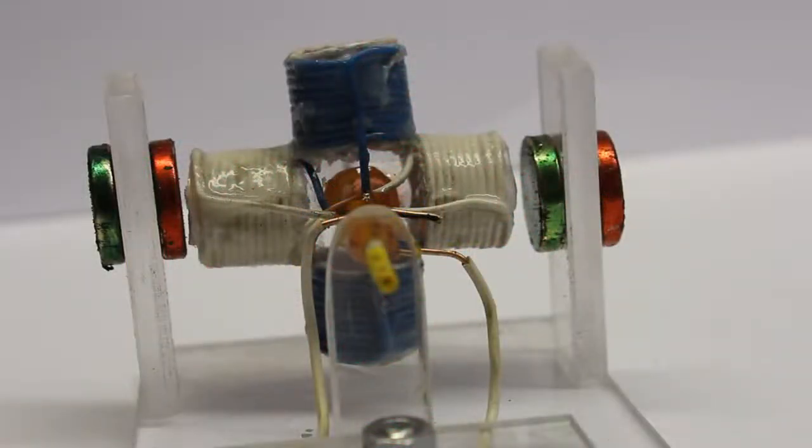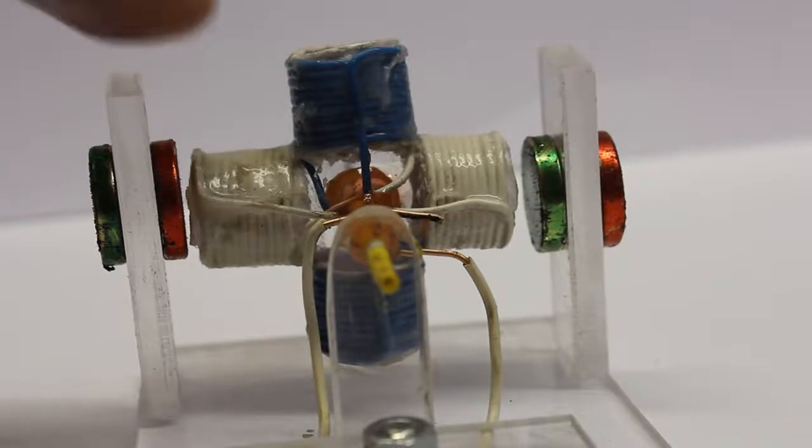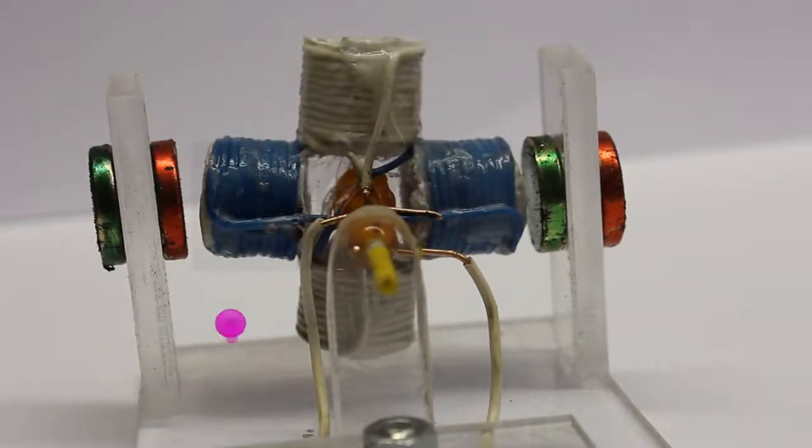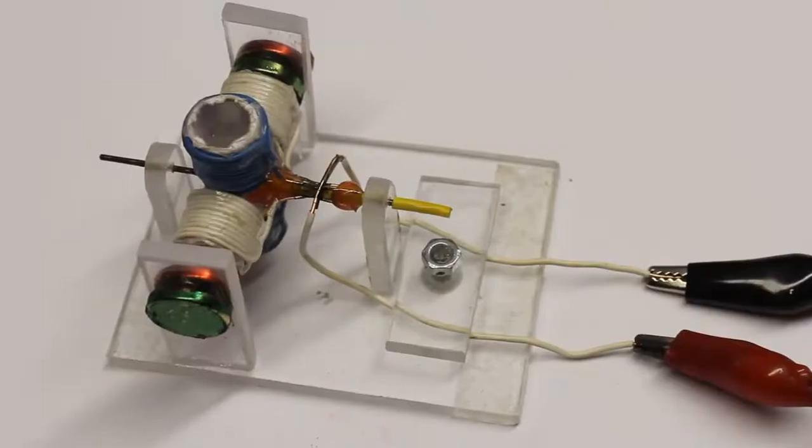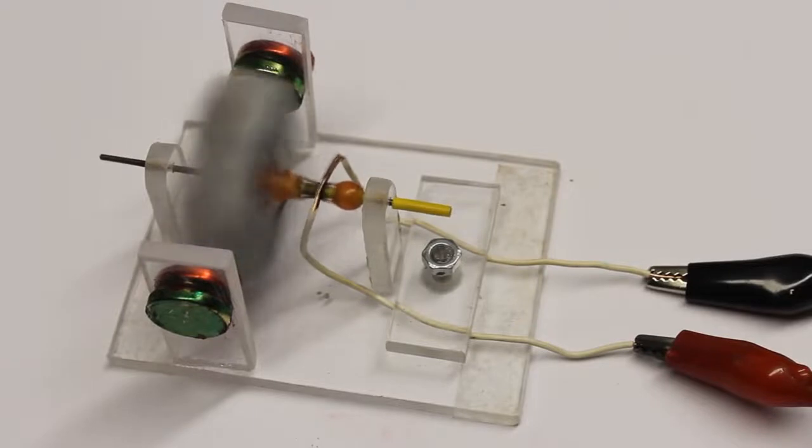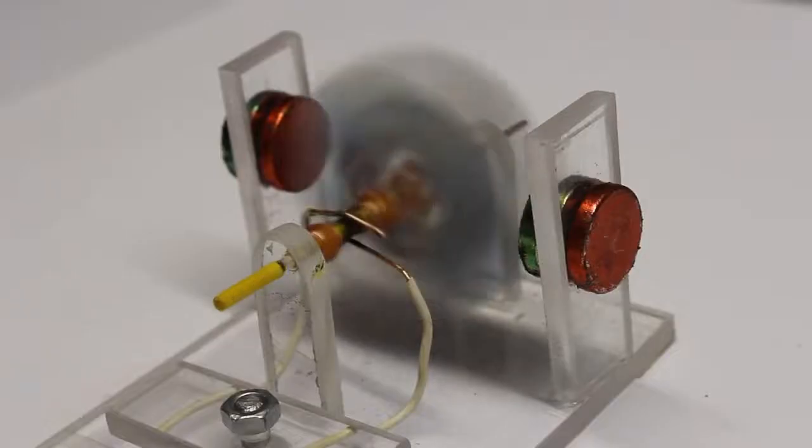Let's prove the predictions with a real motor once again. Note that the copper wire is wrapped with same winding for both coils. When going from left to right, the wire runs from top rear to bottom front, same as in the animation sequences. That's also true for the blue wire forming the second coil. As predicted, the motor spins clockwise with the positive terminal at the left brush of the commutator. Even when stopped under load, the motor continues spinning as soon as it is released.